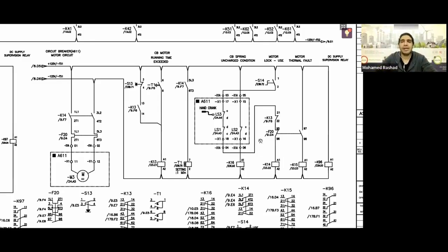Great, excellent. Now, if I want to energize it, what should I do? Well, let's go step by step. I'll start from the top here. Here's the positive. Follow along with me, and I'll come down here like this. All right, and as I come down here, I'll immediately find something called S14. What does S14 tell you? First, S means switch, selector switch, which has more than one position, like 1, 2, 3, and so on. This selector switch has 2 positions, either lock or use.